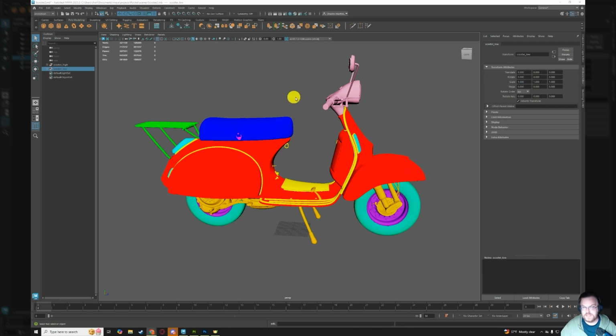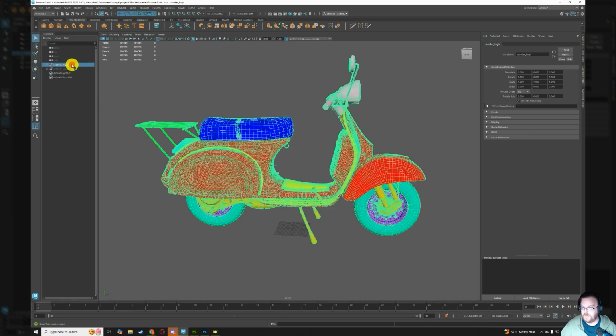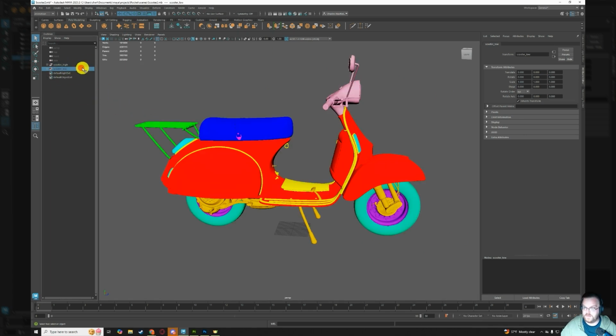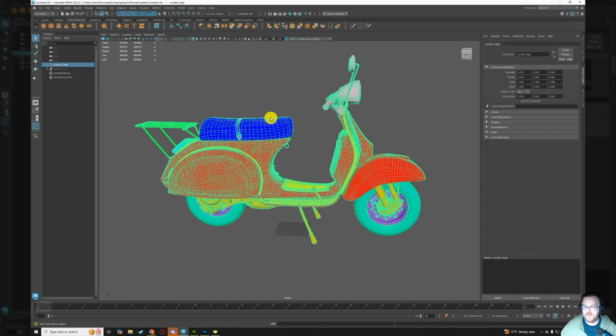So the first thing that we're going to do in this video is we're going to bake our model. What do I mean by baking? In 3D rendering, we have a lot of very fine detail that can take up a lot of polygons. It can be represented in the material using things like height maps and metallic and roughness and different channels within the material to kind of fake the actual detail. And that's good because that'll save us on a lot of polygons.